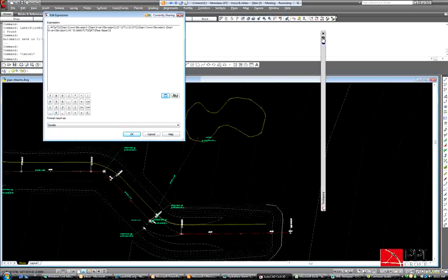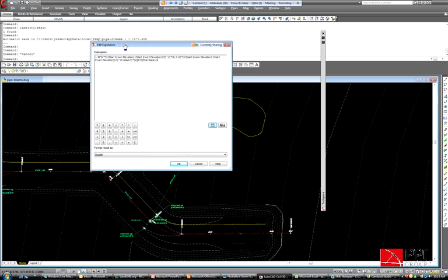Most of the label styles, when you bust into them in the settings tab in the toolspace, you can write these sorts of expressions. So you can see here I've just written it for Manning's equation. I'm not sure how clear, hopefully relatively clear that's showing up, but it's pretty simple. Everybody knows what Manning's is. And you can see in here the insert properties.